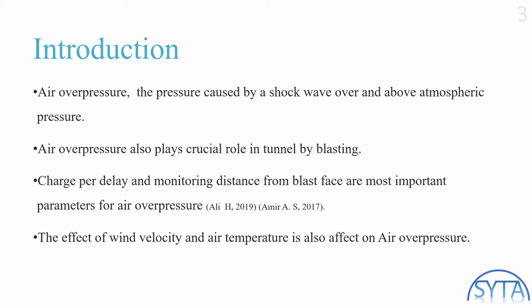Introduction. What is air overpressure? The definition of air overpressure is the pressure caused by the shock wave which is above the atmospheric pressure. Air overpressure also plays a very crucial role in the tunnel, and is caused by the blasting activity inside the tunnel. According to Ali in 2019 and Amir in 2017, the two most important parameters for air overpressure are the charge per delay and the monitoring distance from the blast face. The wind velocity and the temperature also affect the air overpressure.